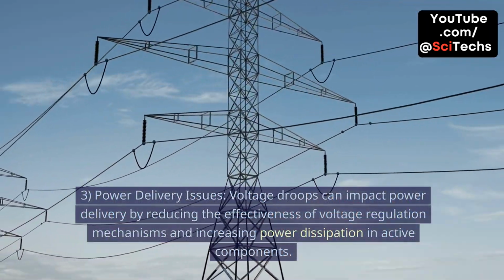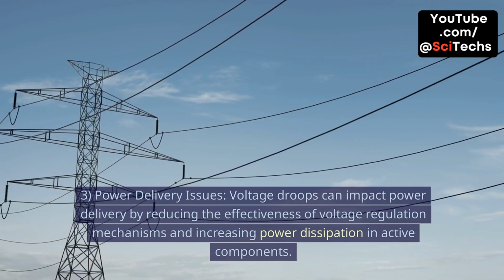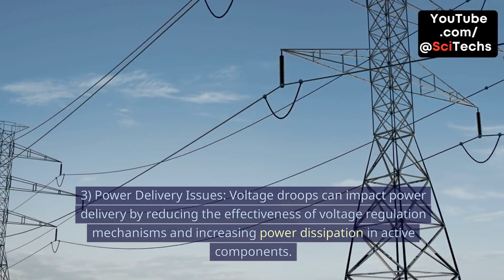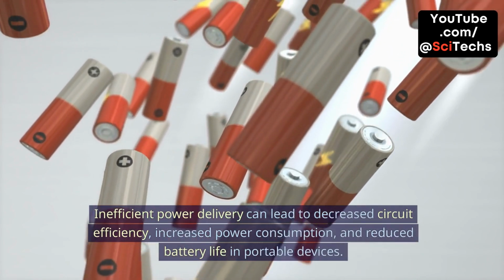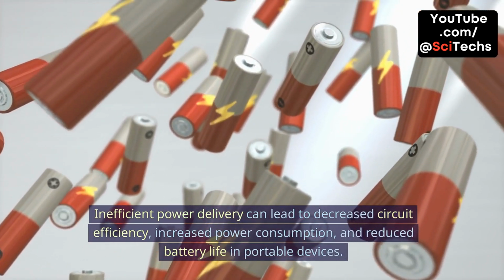3. Power delivery issues. Voltage droops can impact power delivery by reducing the effectiveness of voltage regulation mechanisms and increasing power dissipation in active components. Inefficient power delivery can lead to decreased circuit efficiency, increased power consumption, and reduced battery life in portable devices.